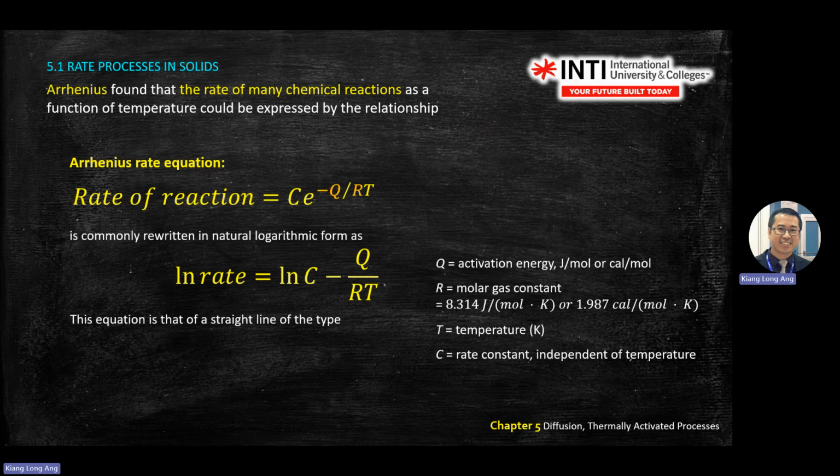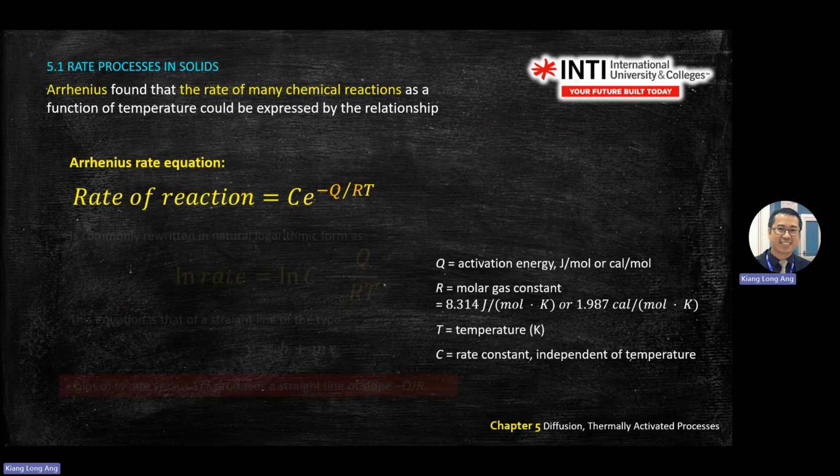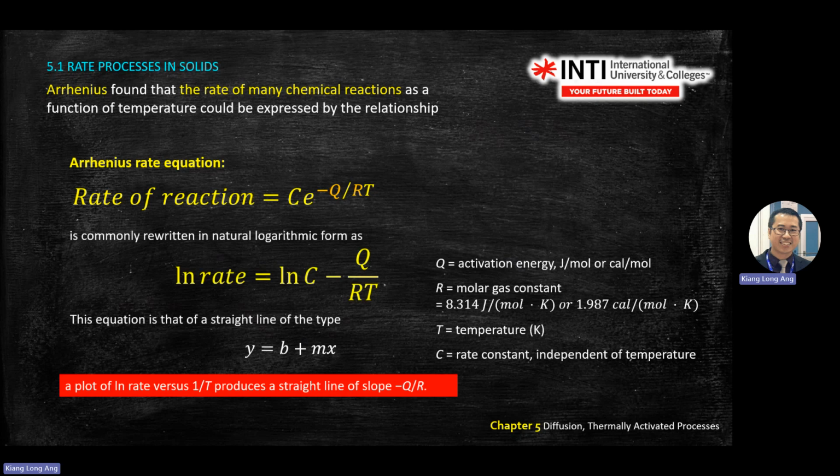This is y equals mx plus c. So you can plot, for reference, y equals log rate. Your x-axis is 1 over T. Log C is your intercept. Y equals mx plus c.